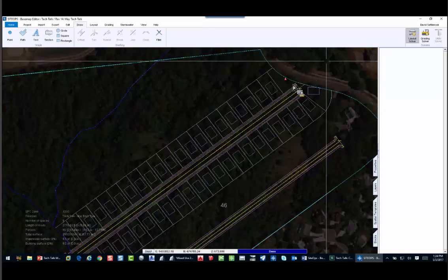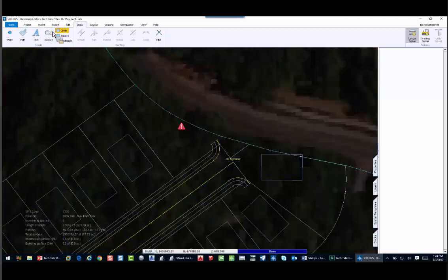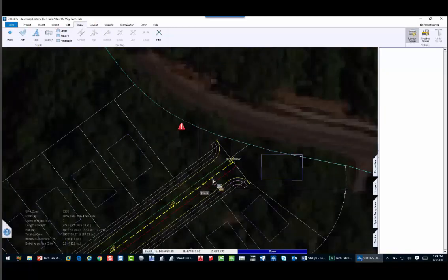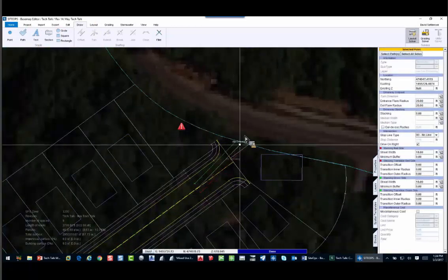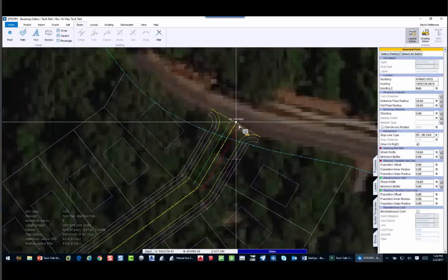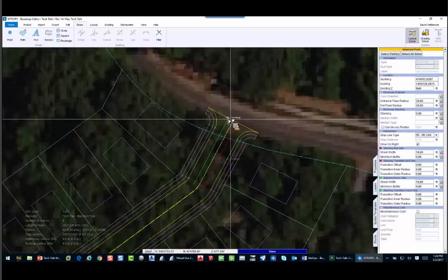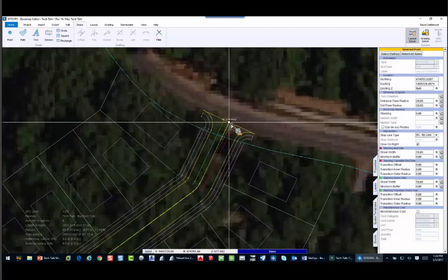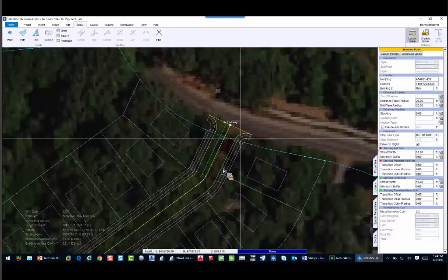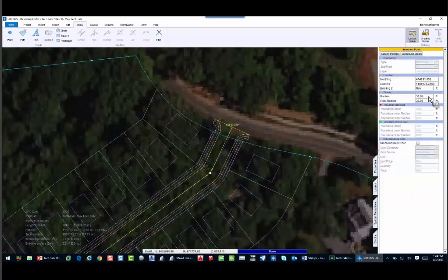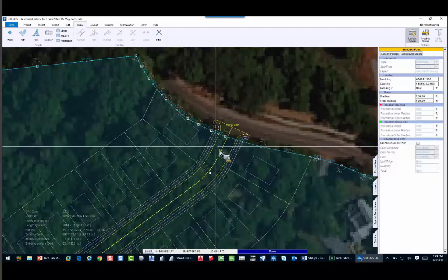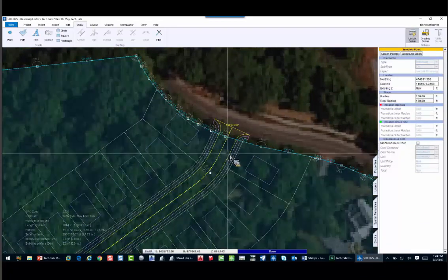I'm going to go up to the top, and we're going to start editing this section. I'm going to draw a point. Again, back to experience. I'm going to move the end of this road, and we're going to bring up the image, and I'm going to tie into the existing roadway. Now, if I had some nice CAD drawings that had line work, SiteOps would tie right into that line work. In this case, I don't really have anything, maybe a little too early in the process. Let's give this roadway a radius. But also, you see these 2 lots in the beginning that don't look right, right?